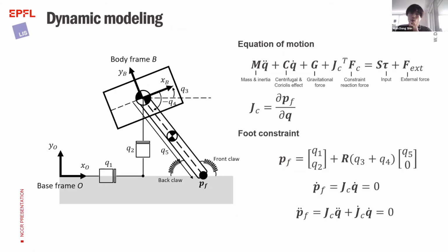And so we need a model to simulate the behavior of the platform equipped with the inverted cam, so we can tune the design to improve the performance. That's why I had to have a model. We used generalized coordinates to model the system. Q1, Q2, and Q3 are for the central mass of the main body. These are virtual DOF, where Q1 is the horizontal displacement in the X direction, Q2 is the vertical displacement in the Y direction, and Q3 is the pitch angle of the body.